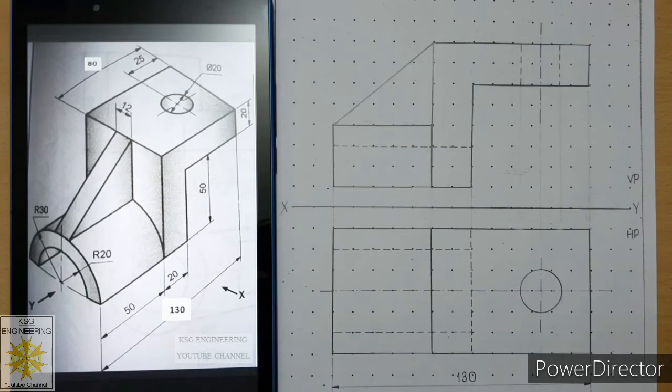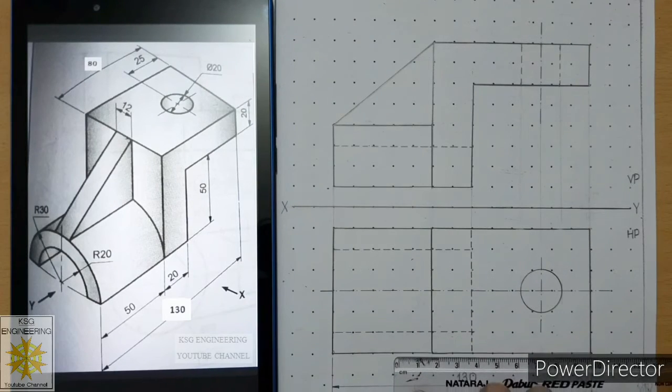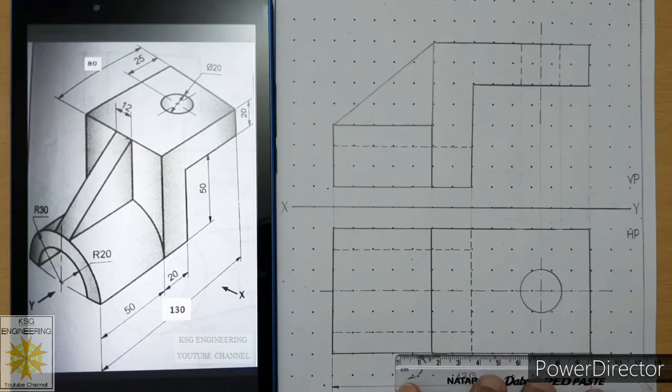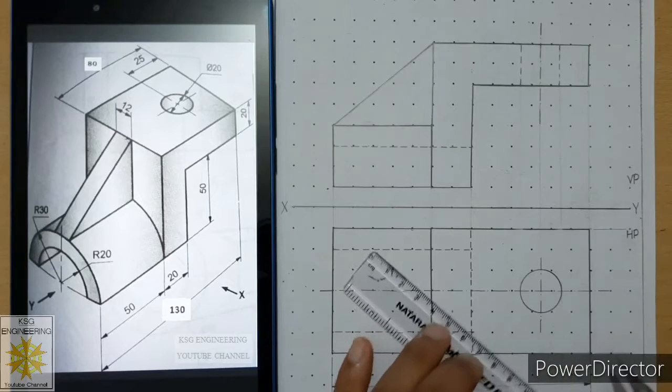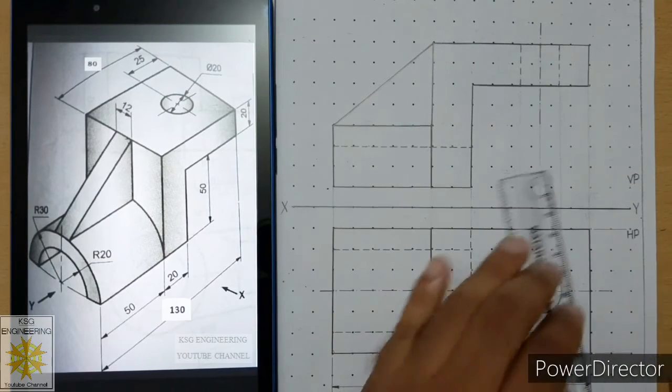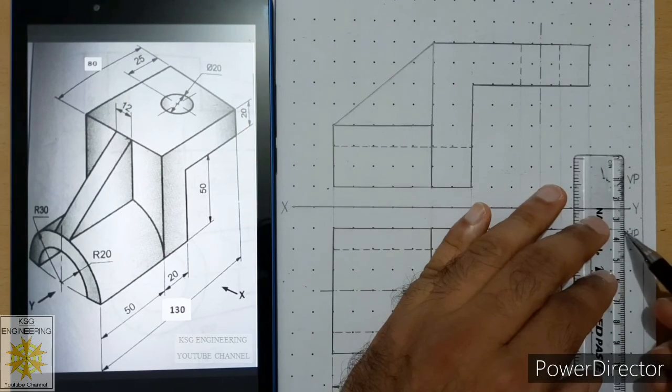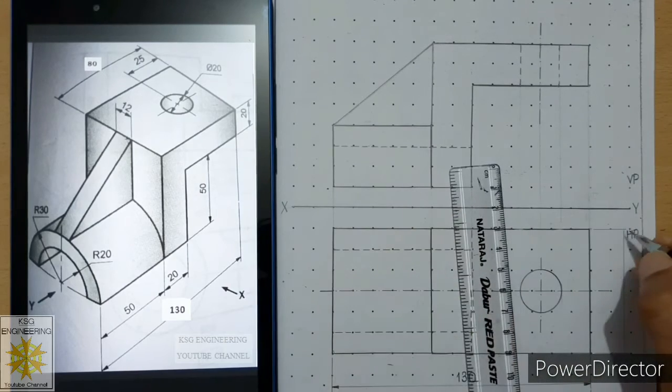So after that we will place its width. So total width is how much? It is 60. So that we can place here continuous thin lines. These are extension lines. Leave 1 millimeter gap first. Then draw dimension line, continuous thin line. Then add closed filled arrowheads on both sides. And over here we will write its value as 60 in Gothic style.